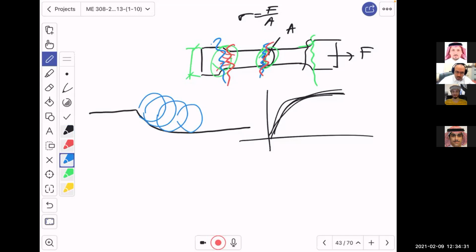If you don't perfect it very well, if you don't control it right, instead of having the profile like this, you may end up doing something like that. Now, that little tiny thing is invisible. You can't even see it. But if you look at it under the microscope, there is an undercut. Undercut means you cut it under the profile that was intended. And there you go, you get failures over there.